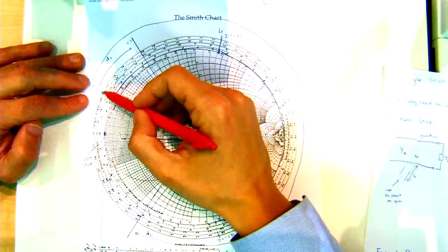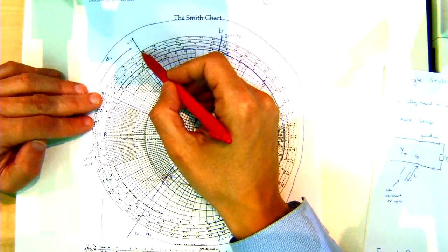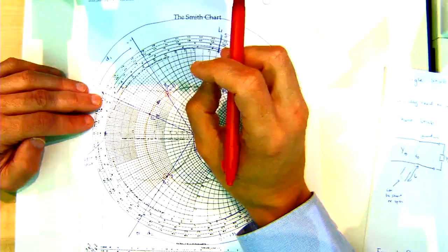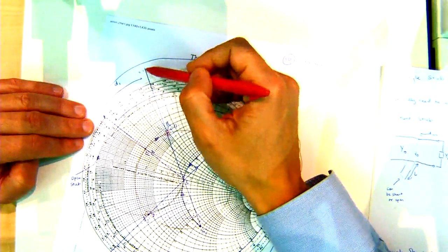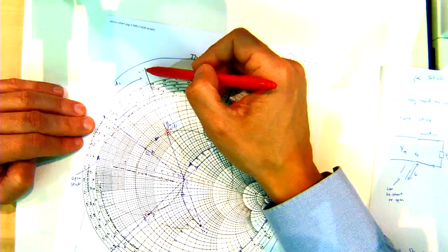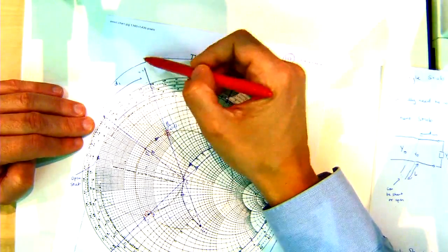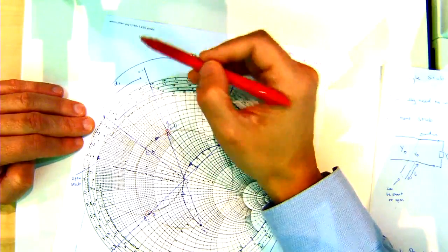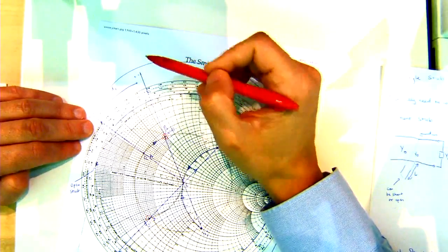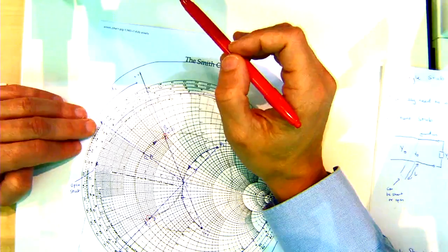So we work out the distance in length here, and it's in terms of wavelength. That's important because it's all relative to a wavelength. So here we're saying distance 1 minus distance 2: 0.78 minus 0.34 is 0.44 lambda. It's giving us the answer in terms of a wavelength. Why is that important?